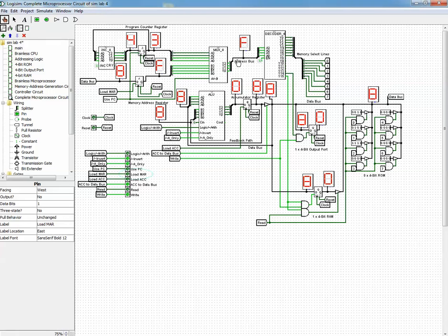Although it might not really matter, because of the delay this 8 might be passed, but I need to set load MAR to 0 so that this F is not lost. And then once we tick the clock, the 8 is stored at this register.